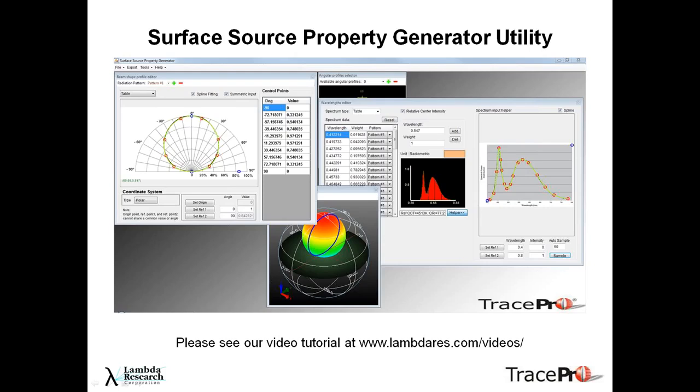And then when we finish that up, we can see some of our results here, and we can actually get an estimate of the CCT, correlated color temperature, and the color rendering index. So we can get a feel for the source even before we've done anything with it. And then we can export that over to TracePro, and it'll insert that right into your surface source property catalog database in TracePro, so you can use that with any of your models in the future. I should note, if you go to our videos section off of our homepage, we do have a couple tutorials on using this utility, some step-by-step videos.